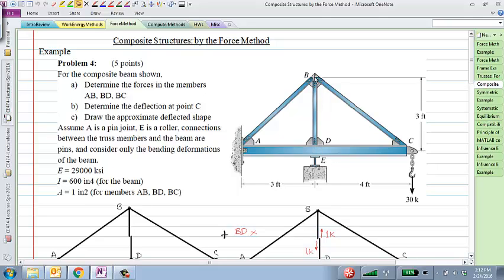It's only when I add this member that it becomes indeterminate. Now you cannot solve for all of those because these members will indeed carry some forces. And since I'm adding one redundant internal force, the degree of indeterminacy of this structure is 1. Okay, so one way to determine whether something is determinate or indeterminate is to write all the equations, write all the unknowns, and see whether you have enough to match up. The other way is what I just did. Take an indeterminate structure and start knocking off elements, and the number of elements you knock off is the degree of indeterminacy. Okay. All right.